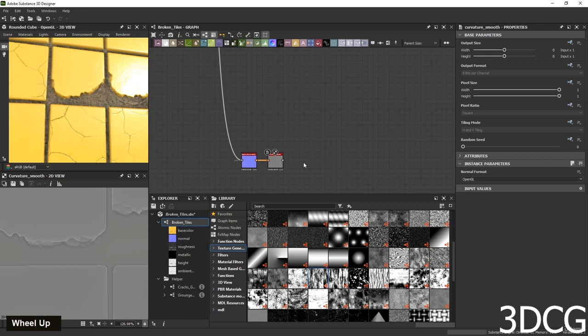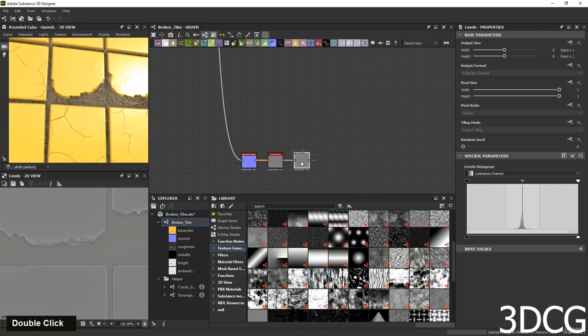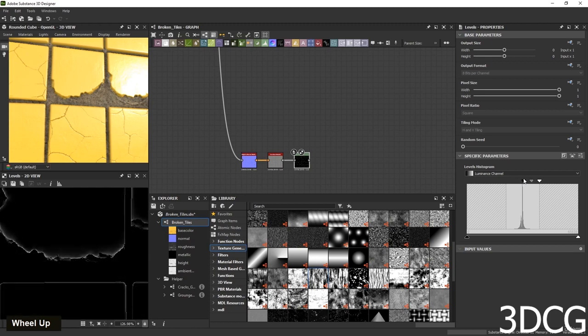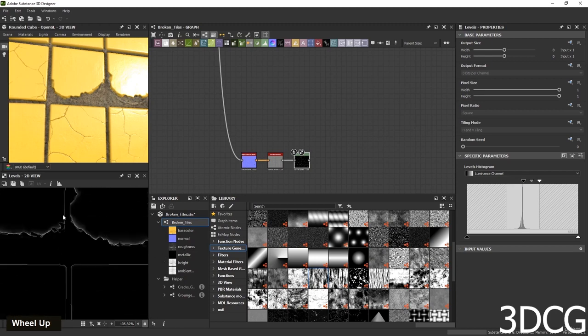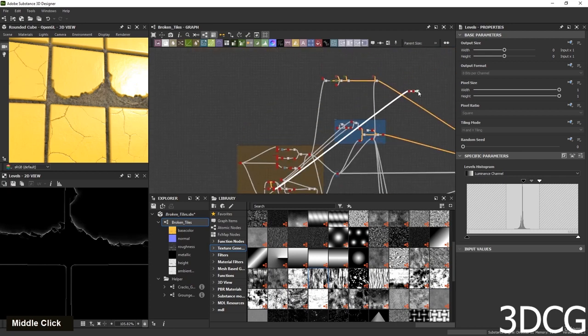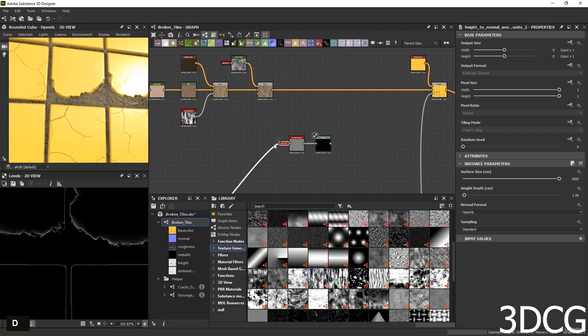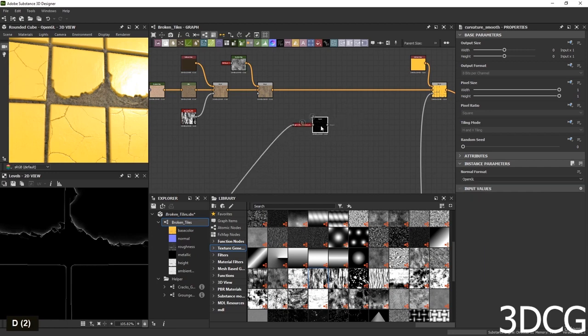Alright, now let's add a level on top, auto level, and play with the handles to target only these edges. So let's grab whole thing and move it up. D and D here.